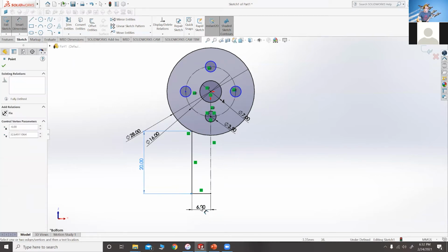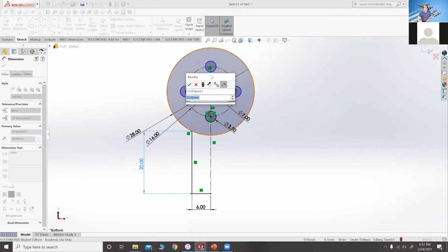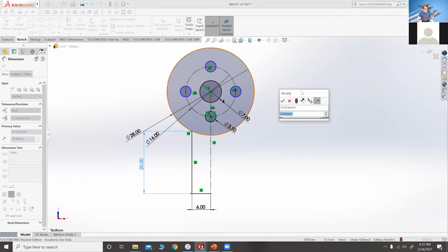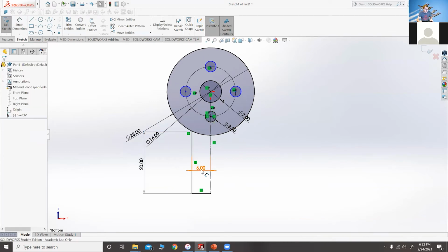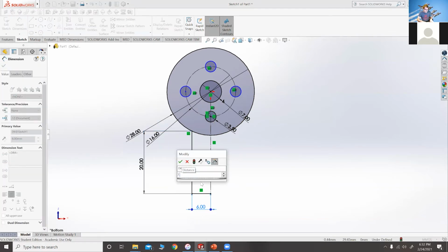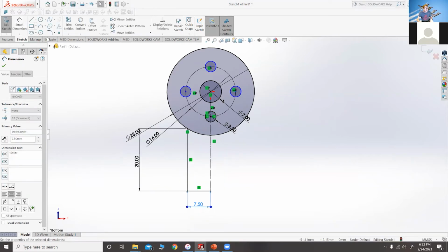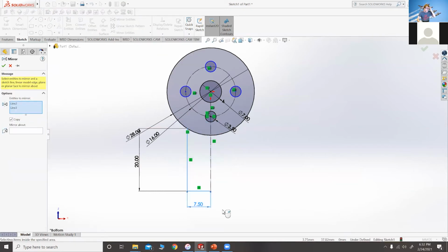So I know that our pylon is 12 millimeters, but I want to have 1.5 millimeter wall thickness around it for the mounting point. So we'll do 7.5. Whoops, sorry, wrong one. 7.5 on here, and this is only the half width of it. And then we'll mirror this. I selected the things we want to mirror, and we're going to mirror about this construction line.